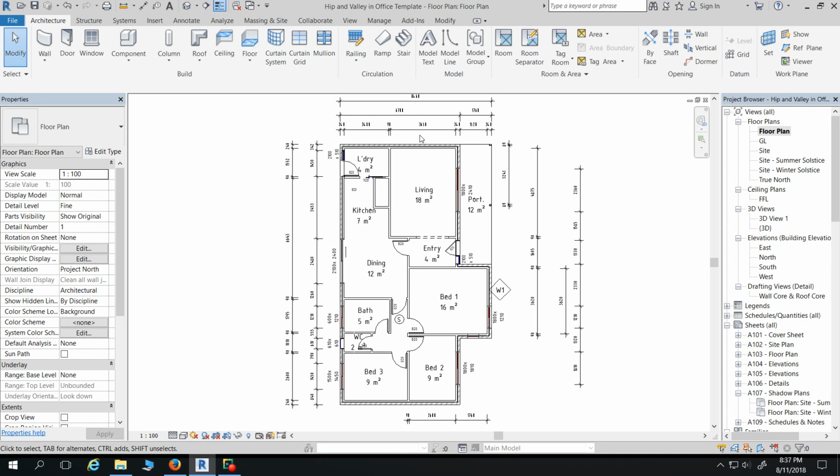This is why I have a keyboard shortcut for fascia and gutter. Because I was like, God, it's so annoying adding. If you add your fascia to that one as well, you can click on the fascia. So just hit modify, click on the fascia you've got already. You can add remove segment. So then it's like one fascia, not two separate ones.